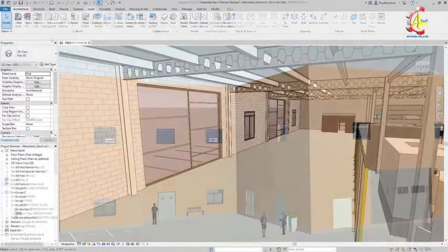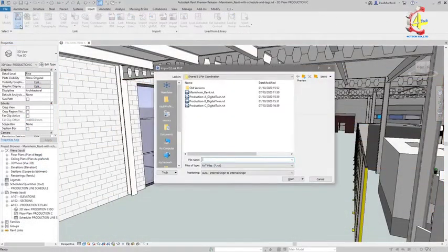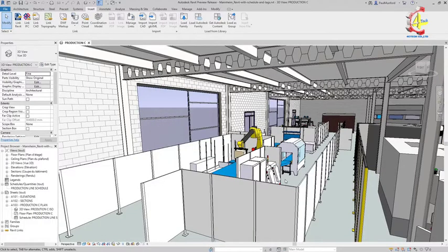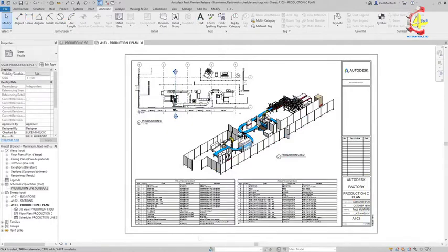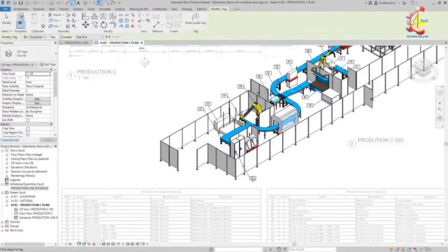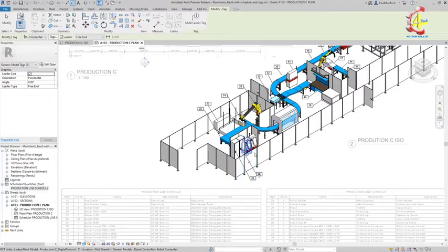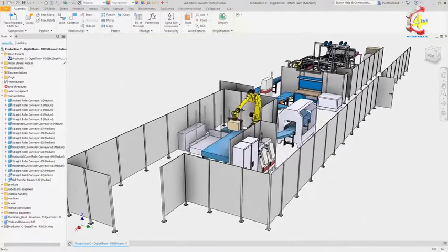project. Our design has been created using a Revit model as reference. This ensures that the coordinate system of the two models match. The exported Inventor model can be linked into the Revit project for coordination and review. Each top-level component has been exported as an item which can be scheduled and tagged inside of Revit, just like